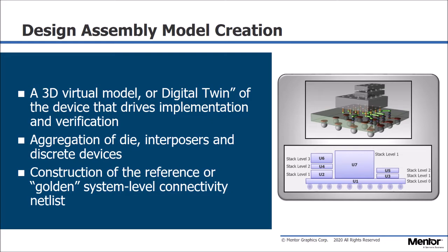Development of the device's 3D assembly floor plan allows you to optimize the assembly connectivity across the entire package design, which lets you look at routability, interface planning, signal integrity and power delivery. It also drives static timing analysis, multi-physics verification and validation of the entire assembled device once design has been implemented.